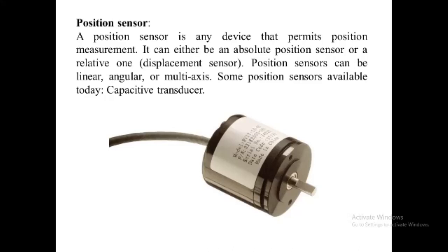One method of determining a position is to use either distance, which could be a distance between 2 points, such as the distance traveled or moved away from some fixed point, or by rotation, that is angular movement. For example, the rotation of a robot wheel to determine its distance traveled along the ground. Either way, position sensors can detect the movement of an object in a straight line using linear sensors, or by its angular movement using rotational sensors.